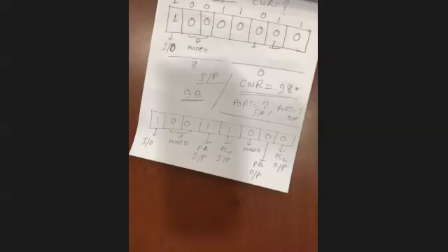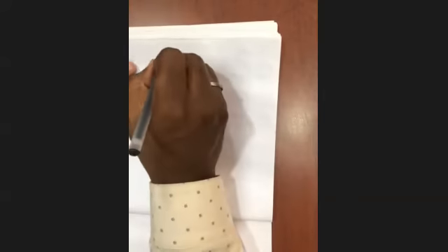So basically, for this reason, we are going to different addressing. It's called IO mapped IO. Those 8255 devices are called IO devices, input output devices. This is not like memory, so it's called IO mapped IO.